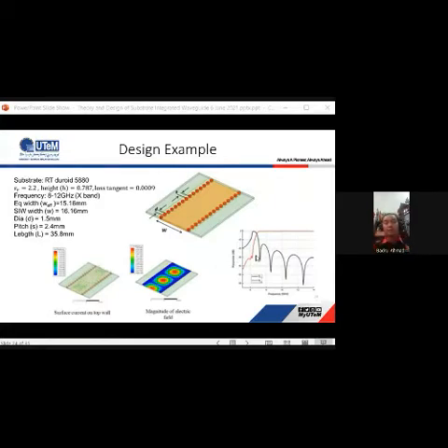You can get this as a normal transmission line, and it is very good, with very low loss. If you look at the current distribution or surface current, you can see how it propagates. I believe the propagating signal is basically the TE10 mode. Okay, next.